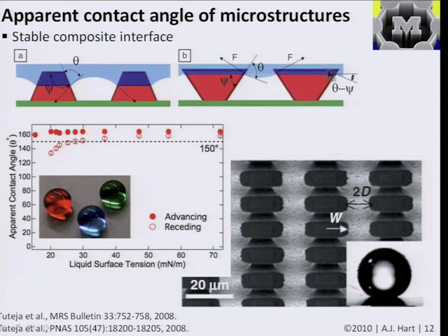But if you look at the contact angle with reference to the top surface like this, the contact angle is much larger, and therefore you would call it a non-wetting case. And basically understanding how the surface energies work together and what the energetic cost is of moving this liquid interface down toward the surface, creating more interface and deforming the meniscus and so on, lets us predict if the overall texture is going to be wetting or not.